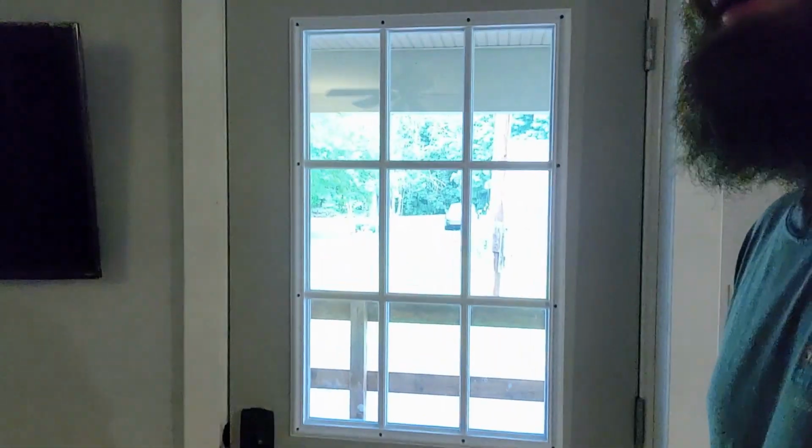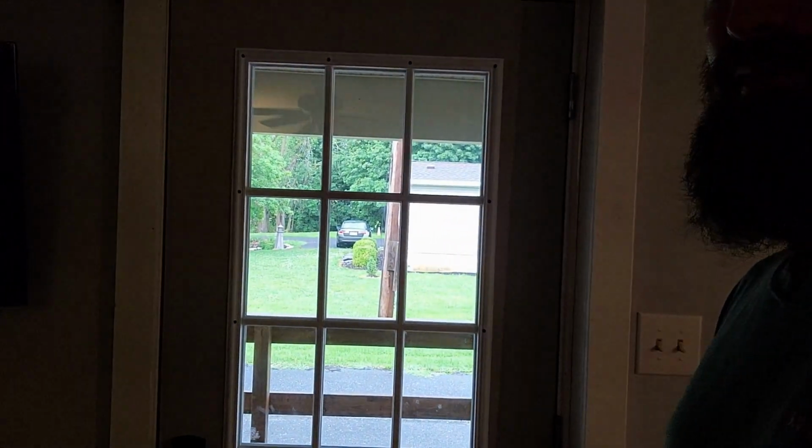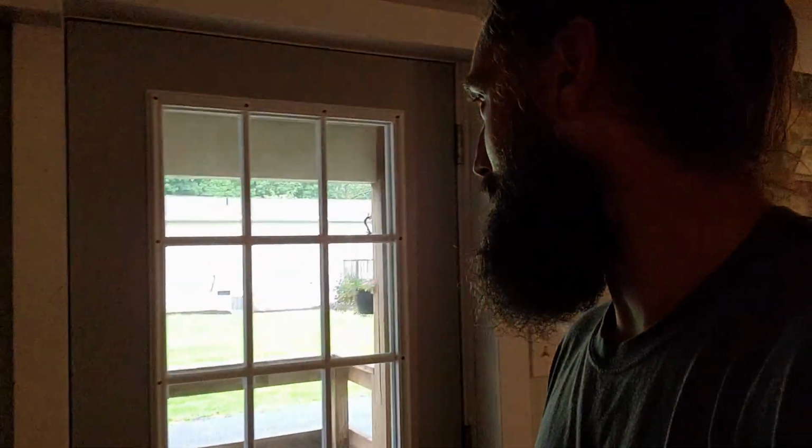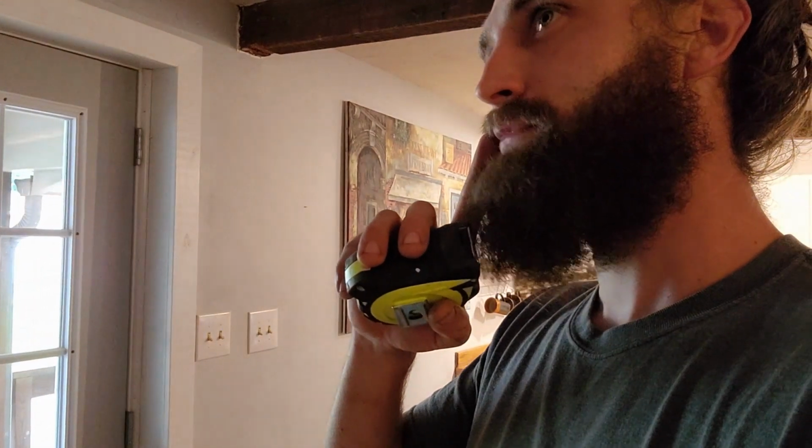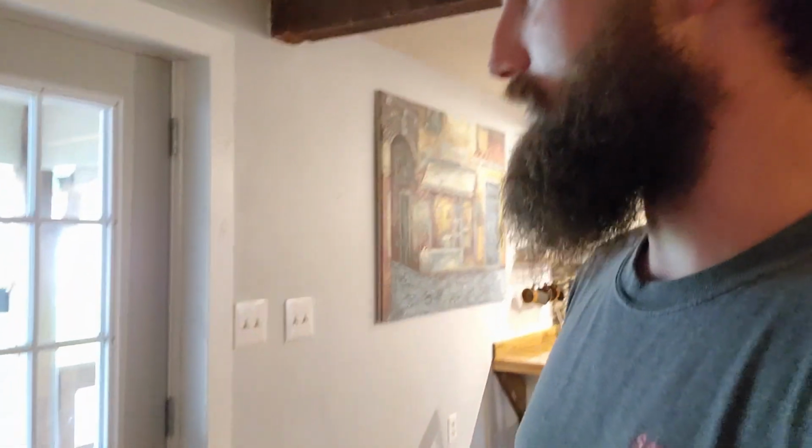All right, so we're going to continue to move along here to the next room, and I'm actually going to look at the entrance door. Okay, so now here's the thing with doors. If I come across a door and it has anything more than 50% of its surface area as glass, I am actually going to treat that door as a window and not as a door at all.